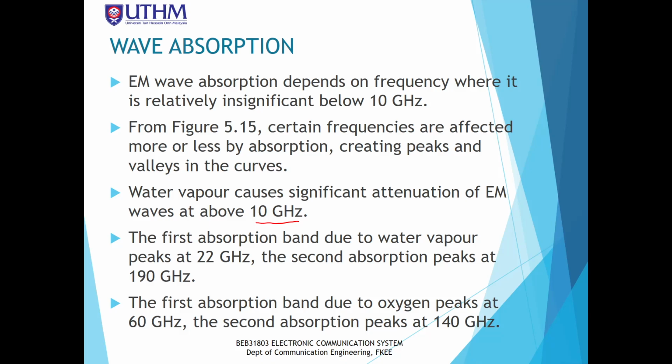It is based on this situation: during heavy rain, as the signals travel from the satellite to your home, the rain will absorb the energy of the signals and the signals will attenuate. Due to the long distance, it will keep on attenuating until the amplitude level drops below the threshold limit. Then the receiver is unable to capture the signal.